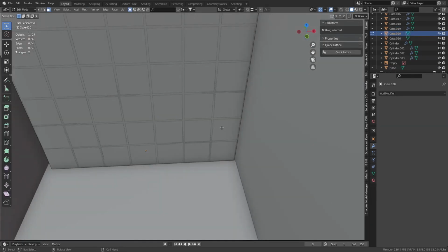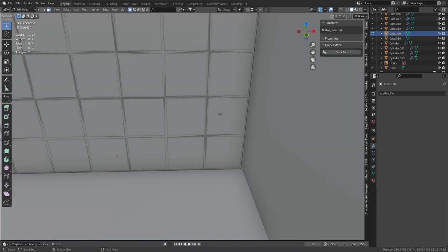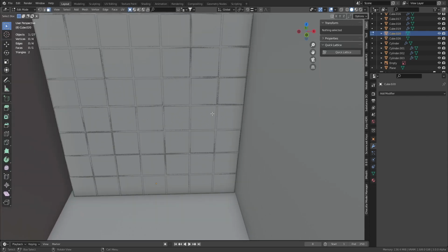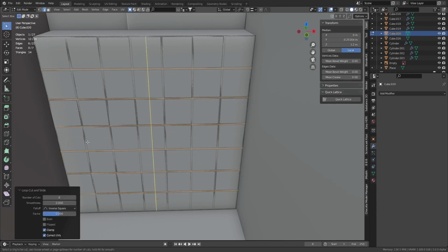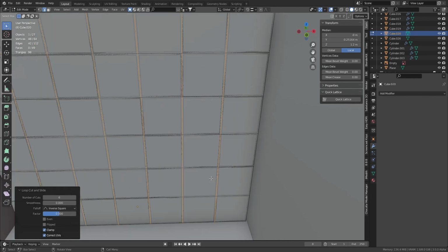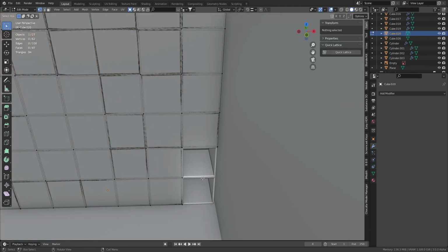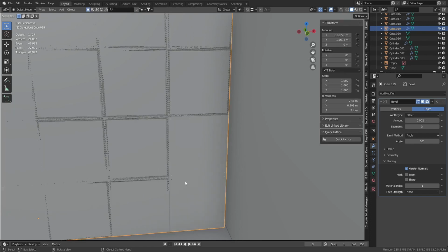So I need to do something for the cloth simulation. I need to delete these 2 right button faces. So I will divide it first as the cloth cabinet. I will make 7 like this and edge loops like this. Then I need to delete these by deleting these vertices. Then I will choose this and I need to fill it. F, select this, Alt select, then F.